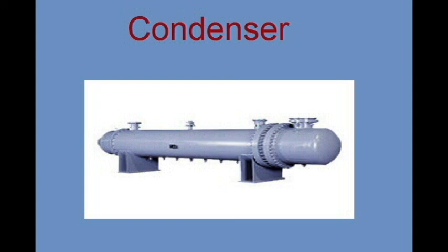The condenser. The purpose of the condenser is to extract heat from the refrigerant to the outside. In ships, the low temperature cooling water, that is water from the LT system, is used as the cooling medium. Onshore it may be air. The temperature of the high pressure vapor determines the temperature at which the condensation begins. As heat has to flow from the condenser to the water or air, the condensation temperature must be higher than that of the water or air.